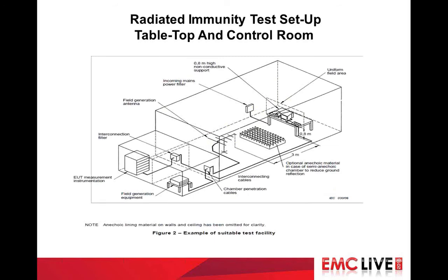Radiated immunity test setup consists of placing the EUT in a shielded enclosure or chamber with a layout that represents its normal operation configuration as closely as possible. Typically, setup includes placing the EUT on a ground plane made from material of the actual environment if possible. A transmit antenna is placed in front of the EUT at a distance specified in the test plan, typically 1 meter for military applications and 3 meters for other applications. The signal generator and power amplifier are set up outside the shielded enclosure. From here they can drive the transmit antenna and the field strength can be established per the test plan. There should be some type of computer to control the test equipment.